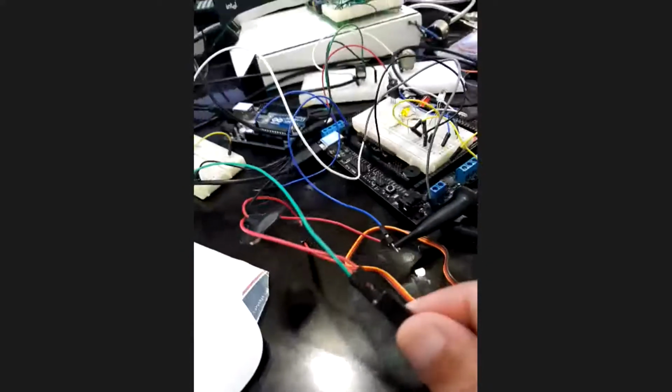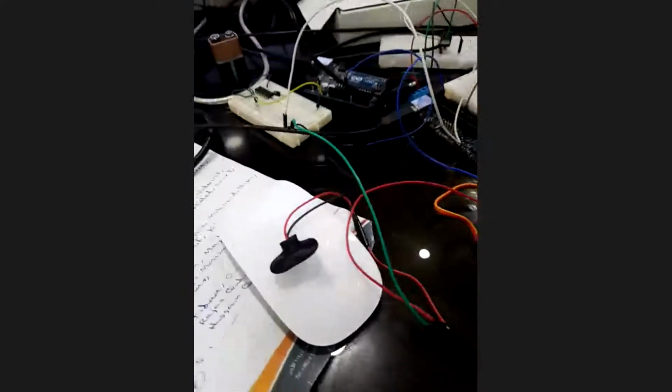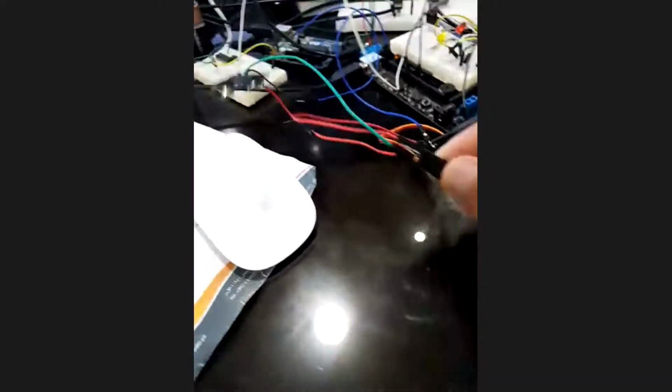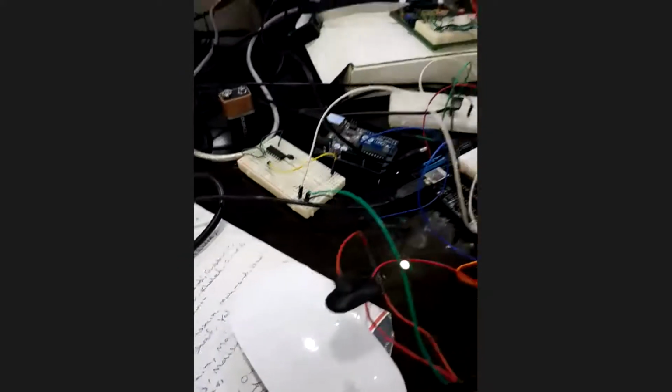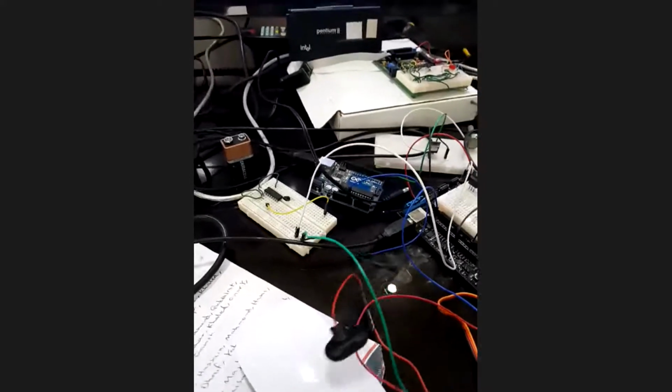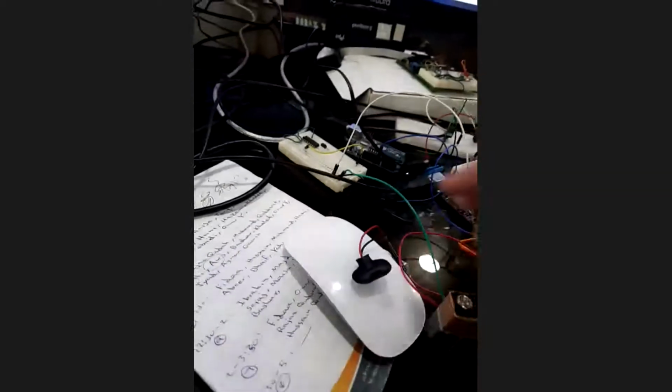Now, if you want to see this on the servo motor, I'm going to connect my servo motor here. Connected red to battery high, brown to battery low, and the orange to port P1, which is the PWM signal. But make sure not to forget the common ground from the battery to the microcontroller, because the PWM needs to have the same reference. Let me get my battery here.